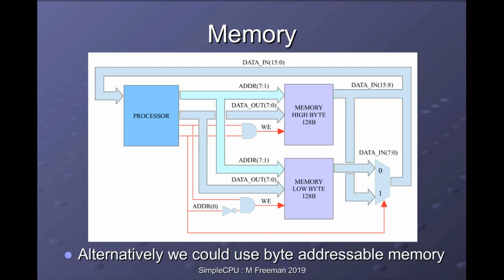take a step back and consider the original CPU architecture. In that original machine, we actually had 512 bytes of memory, because we had 256 times 16-bit memory locations. Therefore, when we go to byte addressable memory, we actually have to halve the amount of memory we have, because we are still constrained by the 8-bit address bus. So now we'll have 256 times 8 bits. If we wanted to keep the same amount of memory, to have 512 bytes of memory, obviously we'd need to go to a 9-bit address bus.